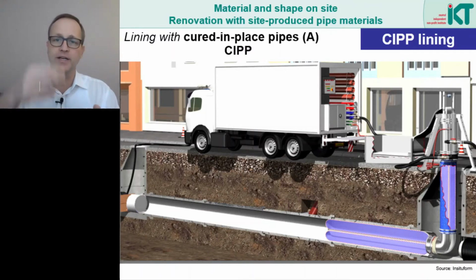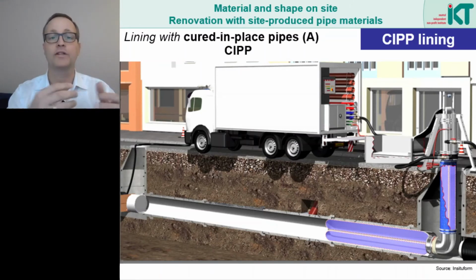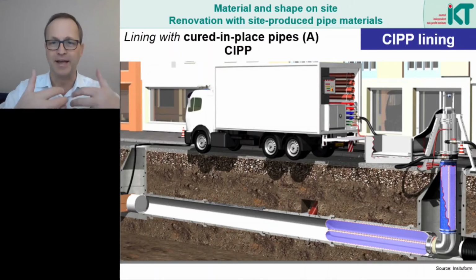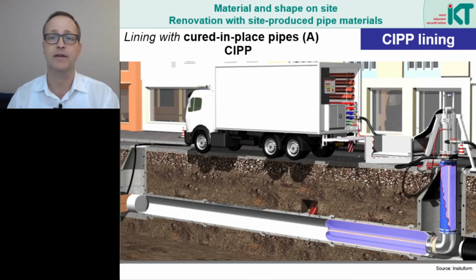The liner material is fed inside the liner and the water is refilled as necessary. The water pressure presses the liner against the pipe wall and turns it inside out. The special advantage is then the new pipe can adapt exactly to the old pipe geometry. With this variant, the resin is cured by pouring warm water into the pipe string at the end of the inversion. In another variant, the liner is simply pulled into the old pipe and then set up using air pressure.